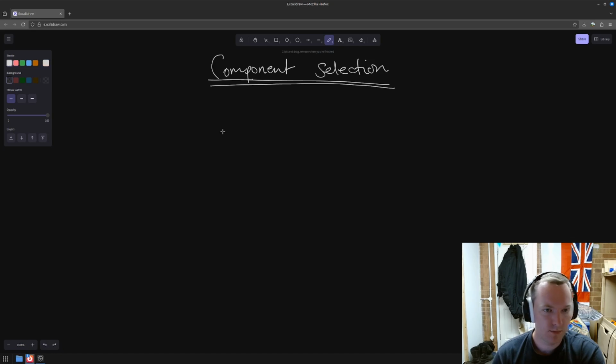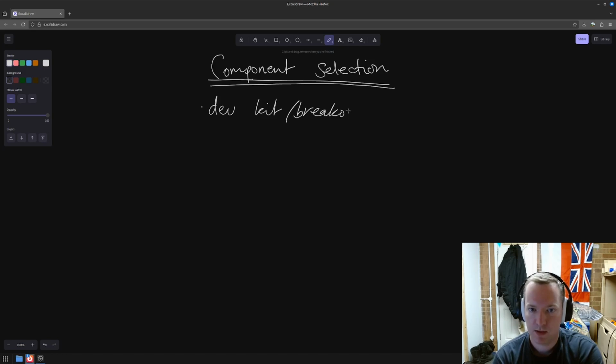take your breadboarded prototype and any dev kits or breakout boards that you've used. Those will almost certainly have some kind of schematic or layout information available online. Or you can always just see what are the major components they've used, which ICs, and basically just check those data sheets. And on that as well, actually, just as part of this process of component selection, you will be reading a lot of data sheets.